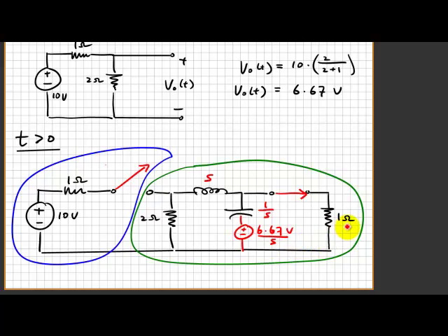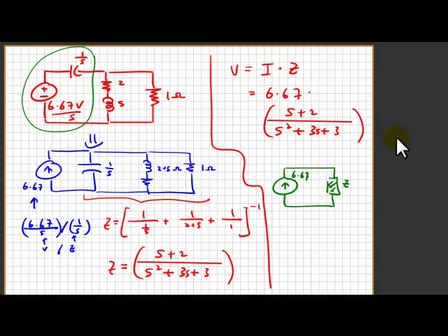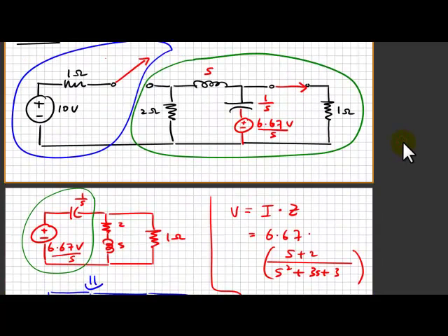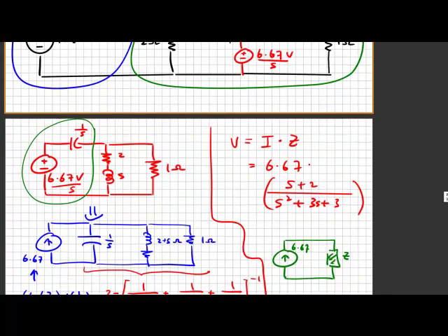Again, there are many different ways to solve a circuit problem. With the calculator that you have now, you can decide what way you want to do to make it simple. What I usually do is simplify the equivalent circuit here. On this next page, you have 1 ohm, 1 ohm, 2 plus s in parallel, and then the voltage source in series with the capacitor. I write it in this way, and what I found is that I can simplify this Thevenin into a Norton, so that it becomes 3 parallel impedances.